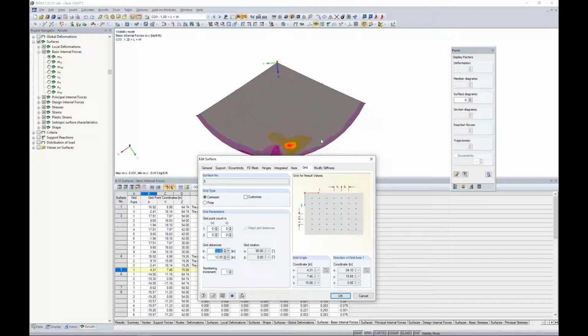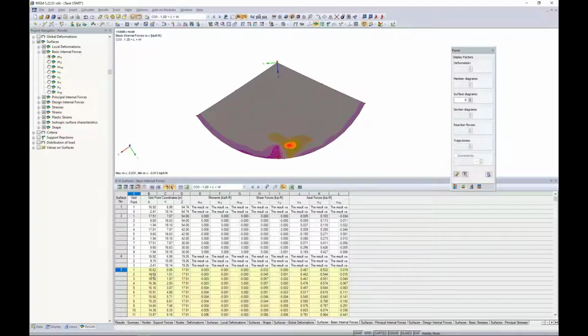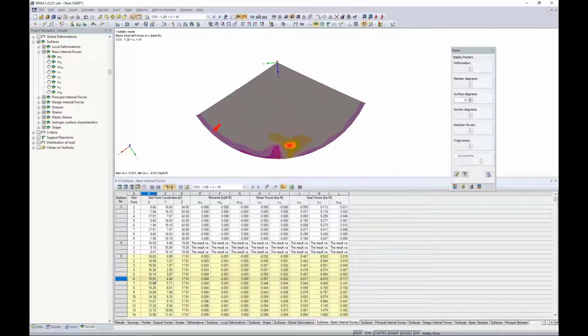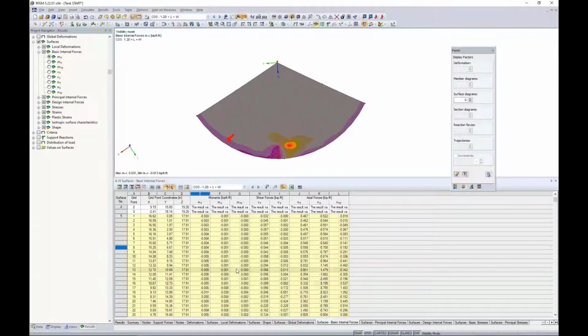Now, this tank structure is fairly small, so we need to go back, and in webinar 1, we did this with the FE elements. We want to do the same with these grid spacings to change this to maybe something like 0.5 inch spacing. And I click OK. So now you'll notice with surface number 5, I have many more points available to me here. So this is obviously going to be much more beneficial than just a single point element.